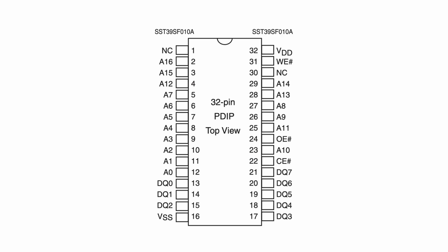Now let's look at the microchip SST39SF010, which is the 128 kilobyte version of the flash ROM chip that I plan to use for the banked ROM. Here's the chip select input called chip enable, but instead of a clock input and a read-write input, we have an output enable input and a write enable input.